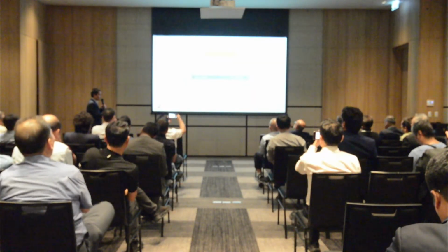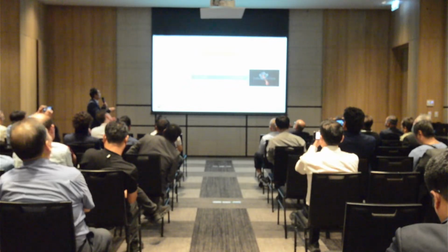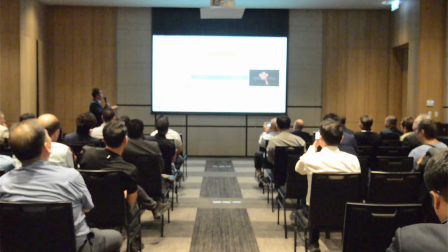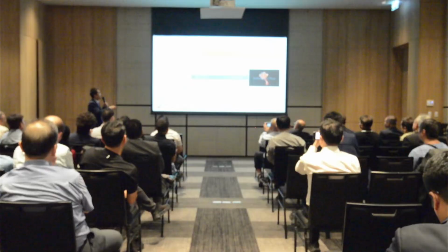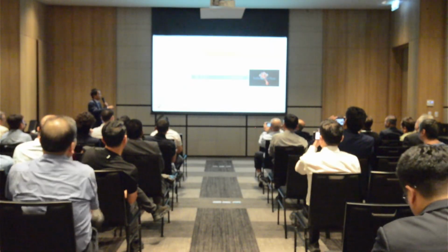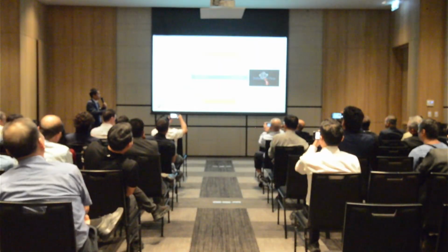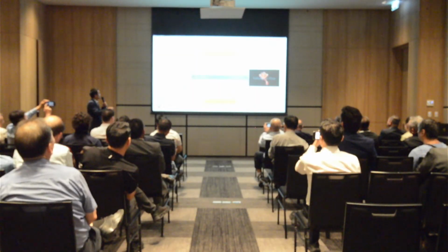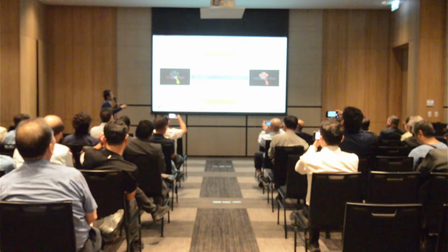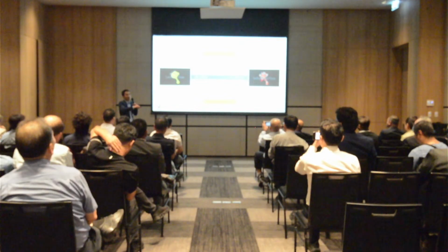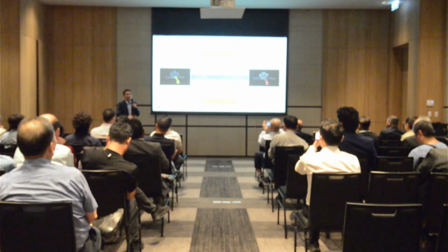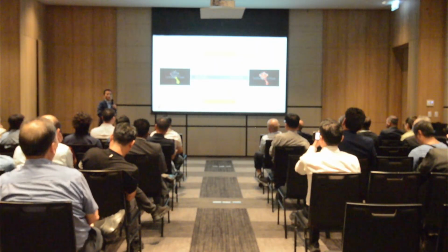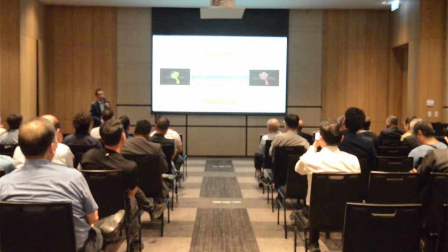And here the difference is the process flow control. For die cast, we normally only care about optimized gate velocity, but we cannot control the viscosity. For slurry, we give you another parameter, which we call viscosity control, to control the Reynolds number. If you want higher solid fractions, higher viscosity, the Reynolds number will be lower, and you will get less turbulence. So this is laminar to turbulence. What we are doing for optimized GISS is between here and here. You can get any fluid behavior by velocity and viscosity control. This is the difference. Normally, if you do HPDC, you only change the gate velocity.